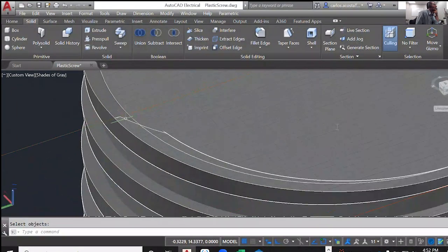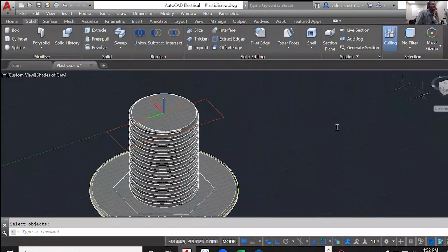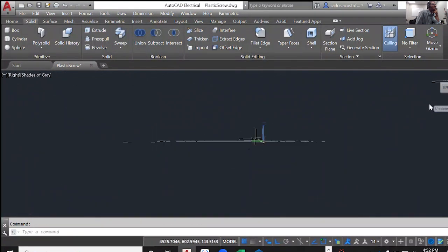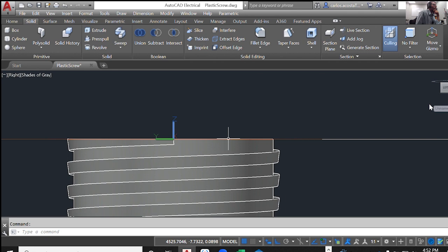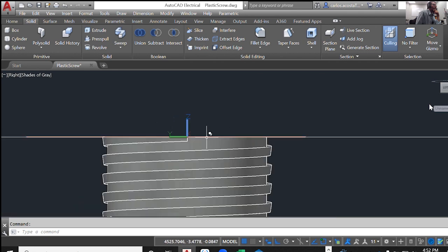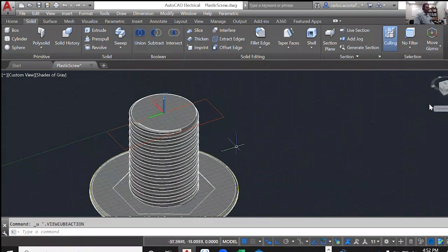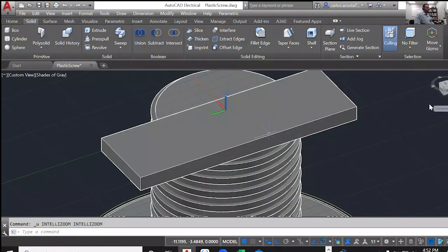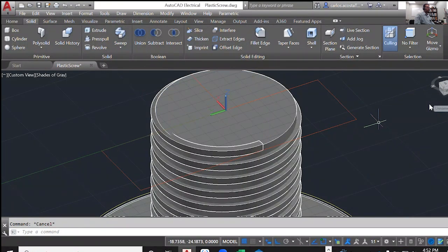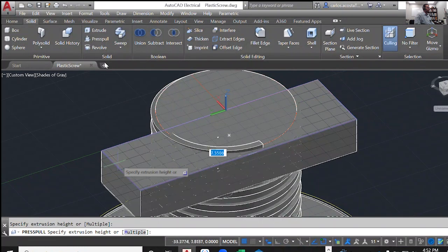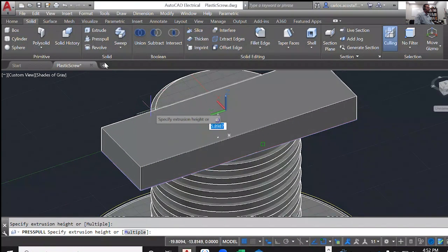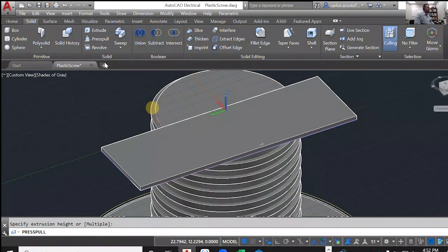So that basically will have, let me see a flush view. So that will basically cut the element. Okay, so what we did was Control Z, let me show you. So as you remember, we had an extrusion of this rectangular shape on top of this plane. We moved the coordinate system up to this point, and when we do a press pull, we choose the rectangular shape, go up enough to cover the excess material.